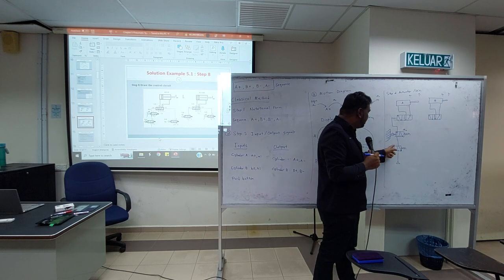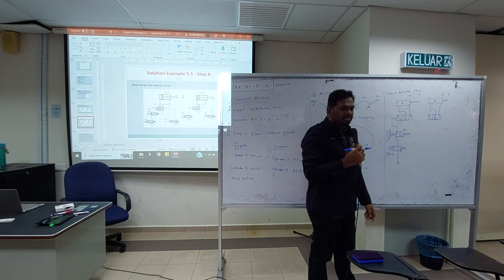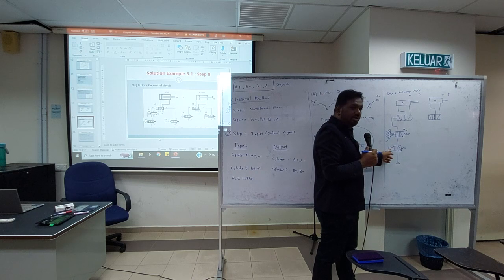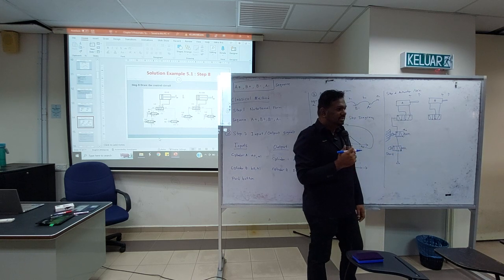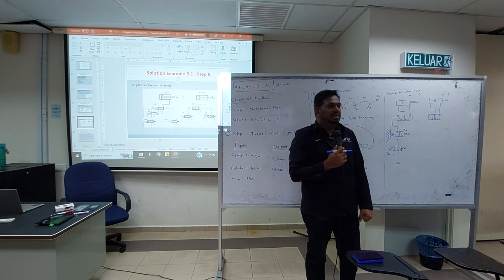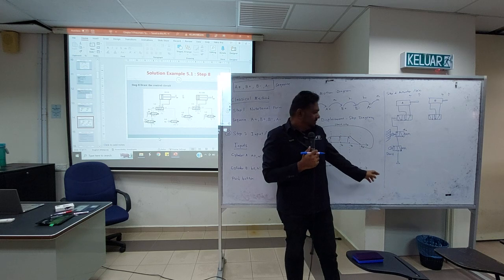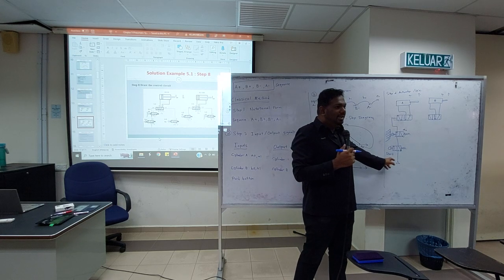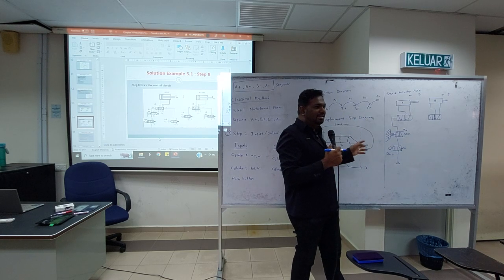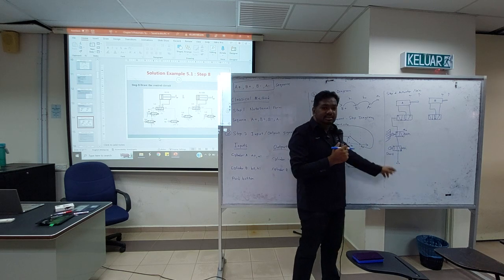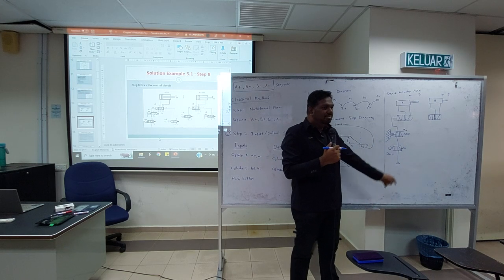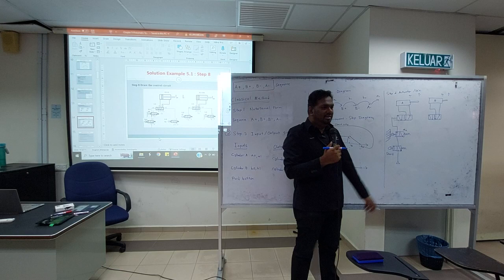So pressure is connected to the working port, so it will supply compressed air to the next valve. If you release, because of the spring, it will go back to disconnection. Do you understand? Who doesn't understand this? If you don't understand this, there's no point explaining the rest. You need to understand this. If you don't understand, ask, and I will explain again.